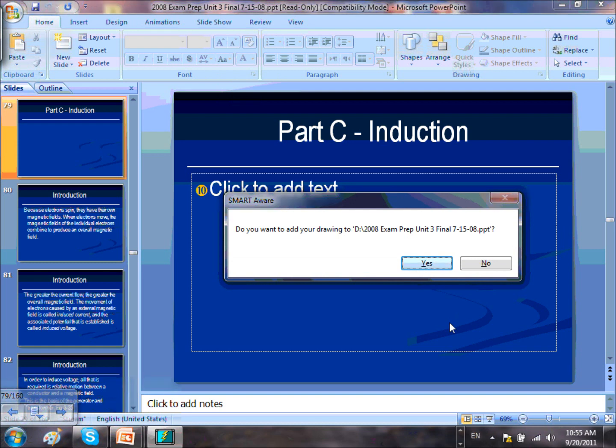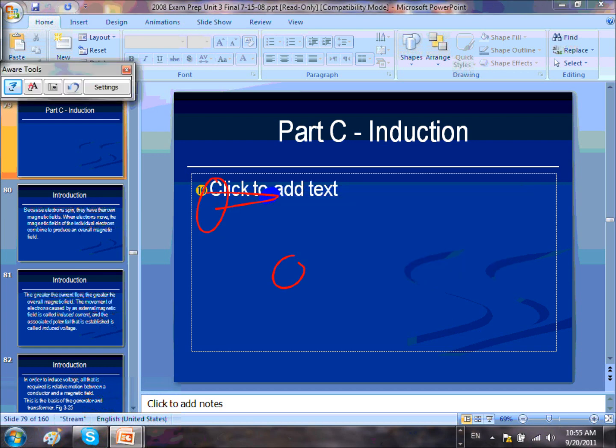Thank you, Chris. The idea of leading and lagging, I will touch on later when we go into correcting power factor, the optimum design. When I say the impedance of a capacitor, I want everyone to understand what that is. When I say the impedance of an inductor, I want everybody to understand how to do that, right? Because later on we start correcting power factor, adding capacitors. Why do we add capacitors? Because we are increasing the XC to reduce the XL. So that's why this is building up to the voltage drop correction later on. Okay, thank you.